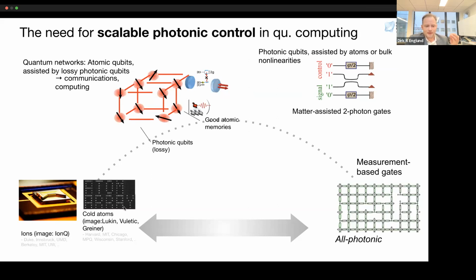So this demands a new kind of laser system that allows something like a gigahertz or so on-off modulation rate, but also with very high contrast. To keep errors low, you want the contrast in intensity to be something like 60 dB. There are no commercially available modulators that can get to 60 dB.